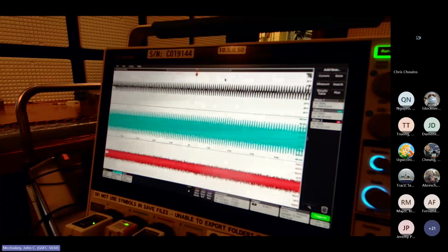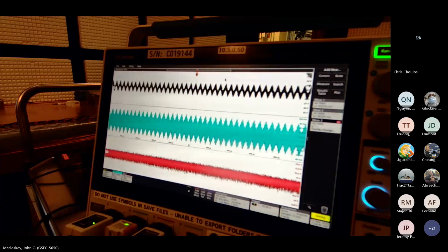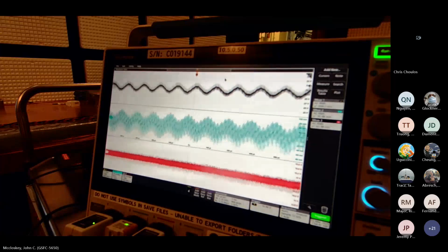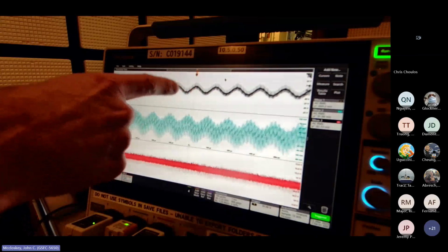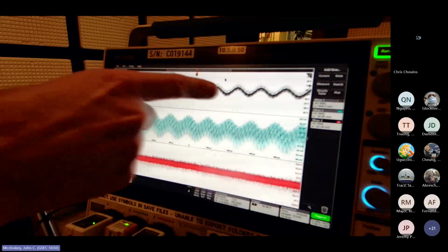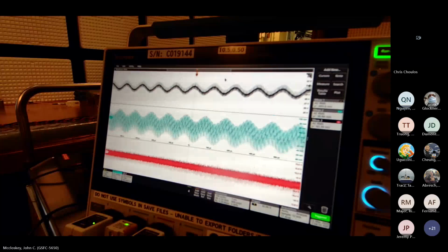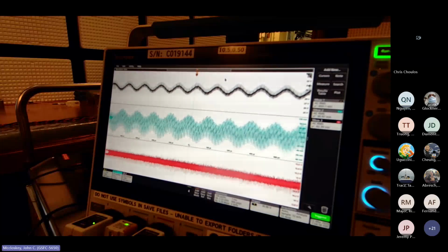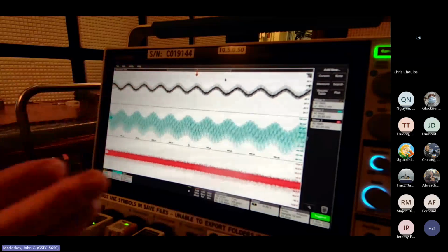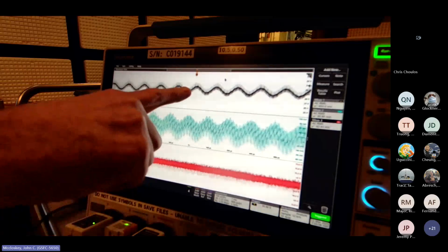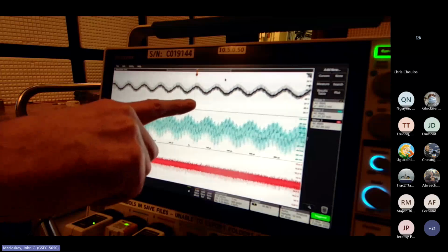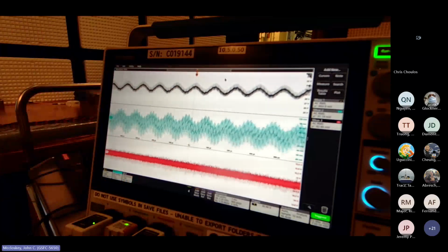And then now we're starting to see the actual switching of the power converter really riding on top of things now. Those big transients there, and in fact, I already know this from having run through this. At 150 kilohertz, it's going to be much more. Those bits of ringing are going to be a lot more noticeable, right?